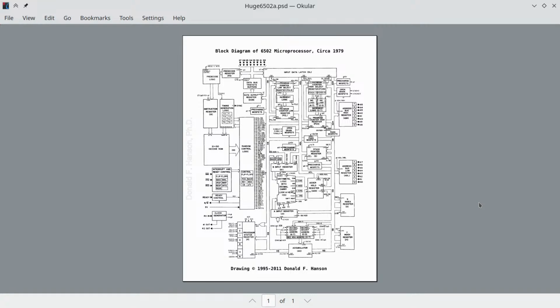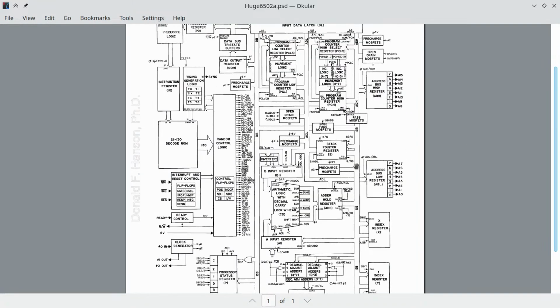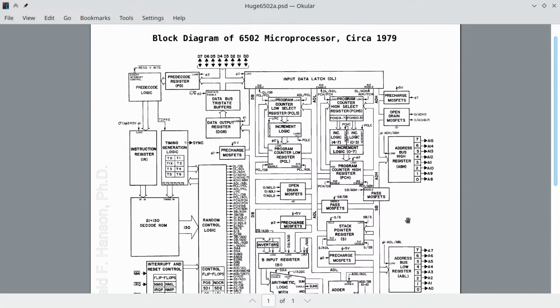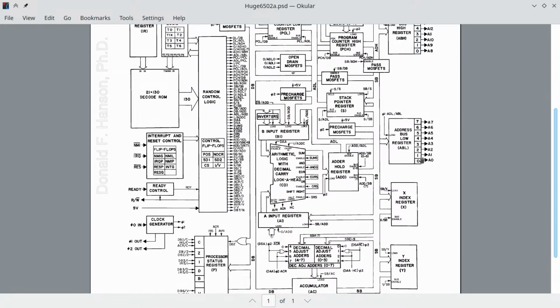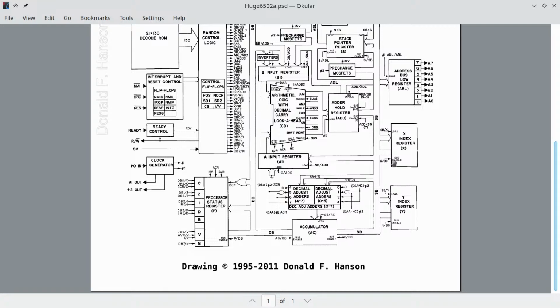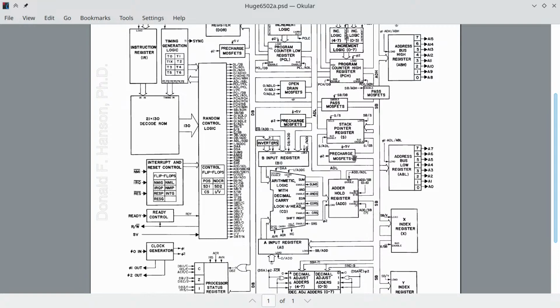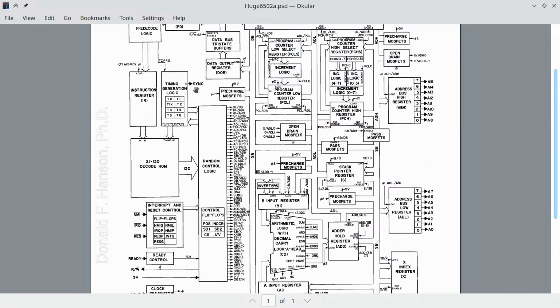Now, the microcode, what we're actually writing, is the control lines going here. So this is the load, which tells the register to get a value, or the bus enable, which tells the register to output the value. These are generated by the decoder logic, which is these blocks here, and can be roughly seen as the list here. Now, our architecture isn't 100% identical, so some of our microcode will be different, some of our control lines will be different, but they're still named under the same logic.